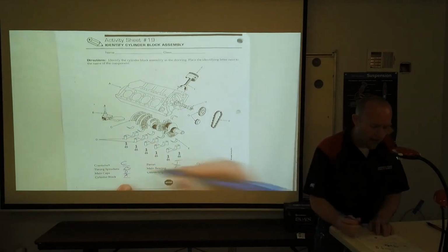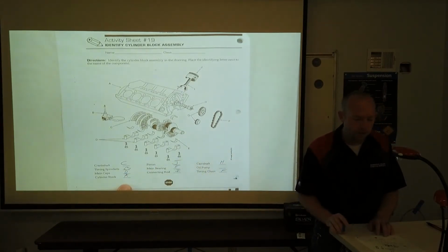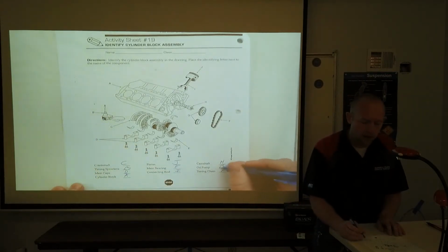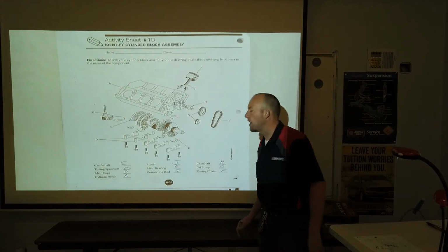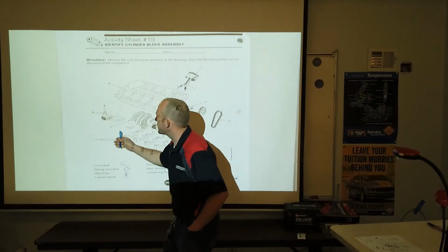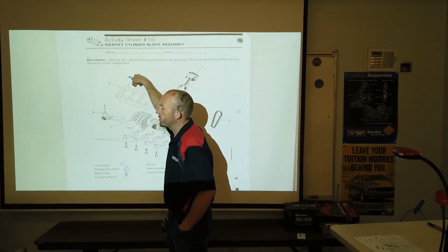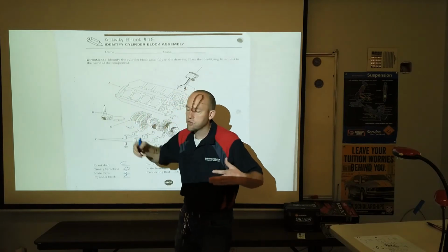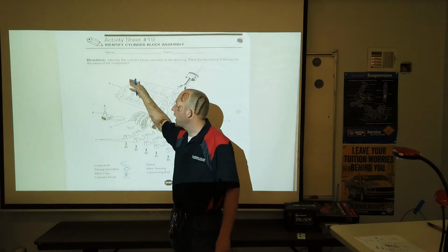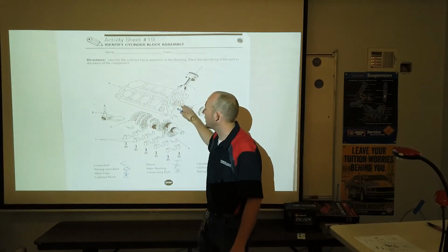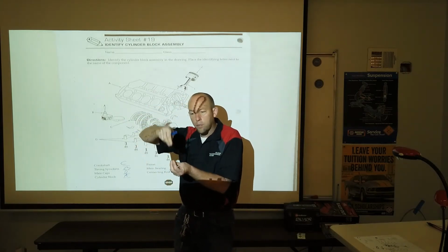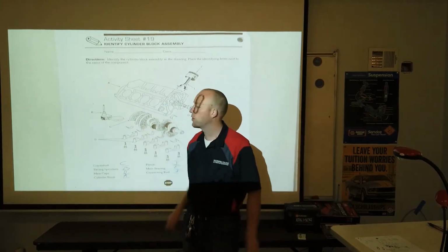Cylinder block is A, and then our oil pump is B over here. So that's our oil pump there. A lot of times oil pumps are going to be driven by the cam in a configuration like this. This would stab up through the back of the block. You have a distributor that would come down and tie into that. The distributor distributes spark on that motor, and it moves mechanically, and the distributor is tied into a gear or sprocket on the cam. Since the distributor is turning and the oil pump is tied into the distributor, that would turn the oil pump as well.